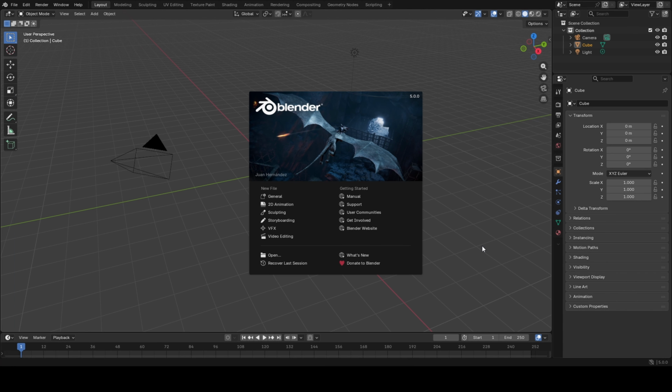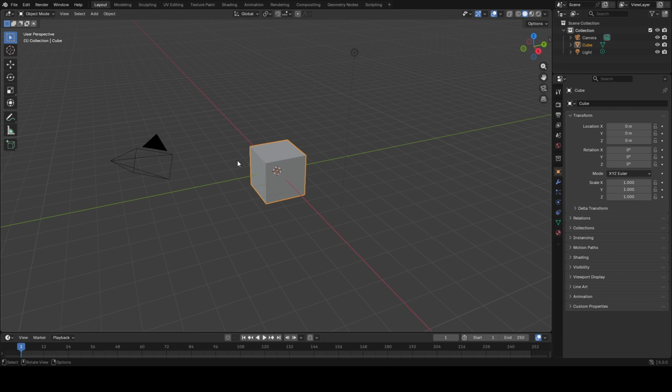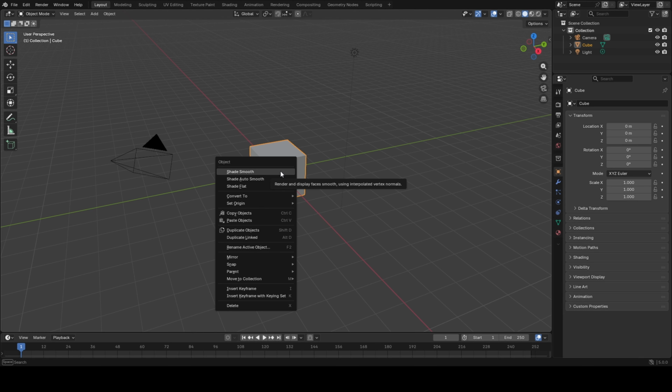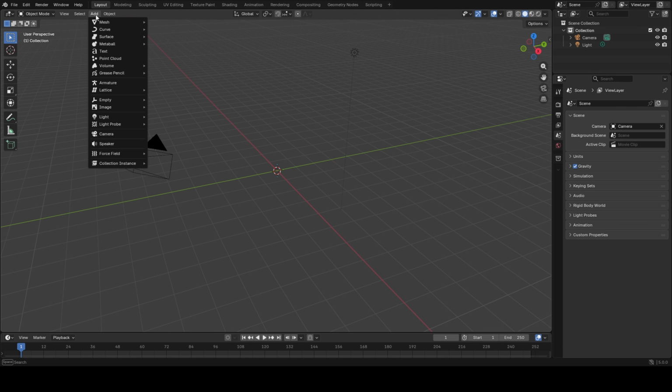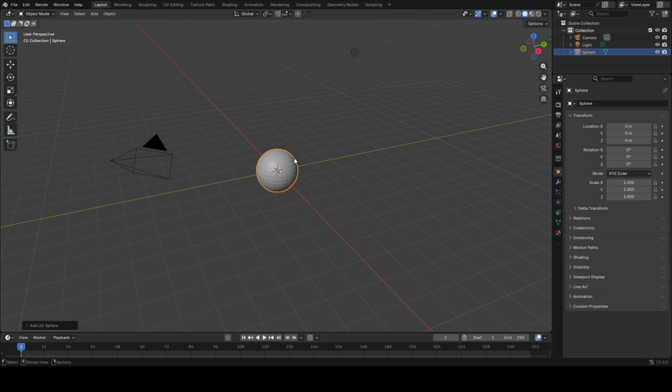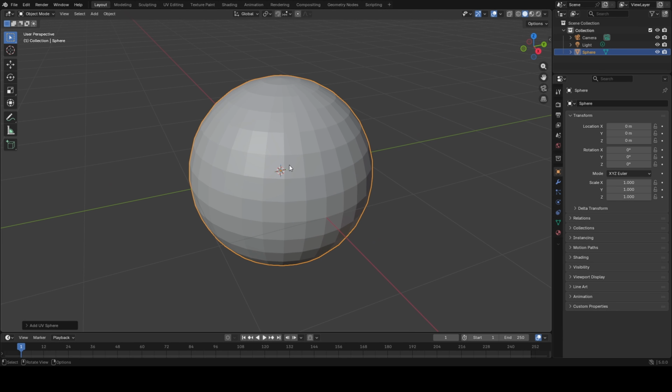And here we've got Blender. If you want, again, I'm not very experienced with Blender, so cut me some slack. You go into your general, you right click, delete whatever it is. You can also change your box to a sphere, but let's make it super easy. You then go here to add, mesh, UV sphere, and here you've got your sphere.